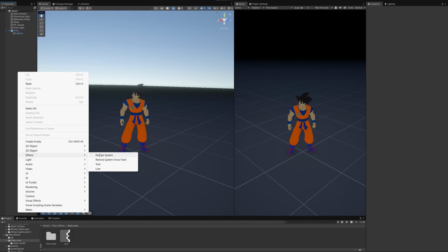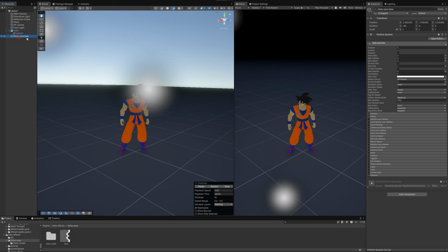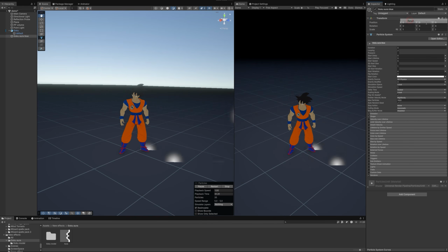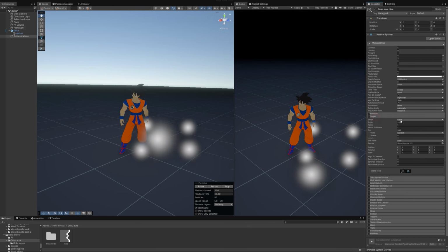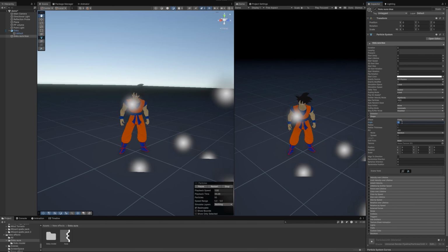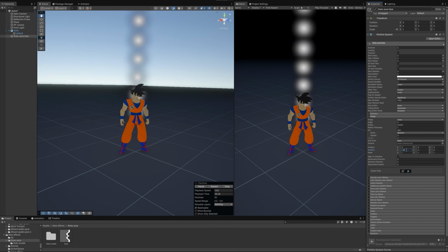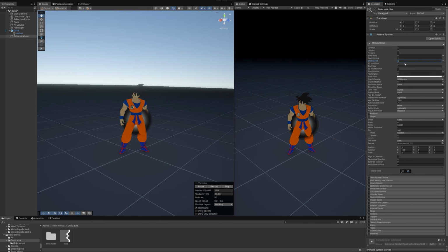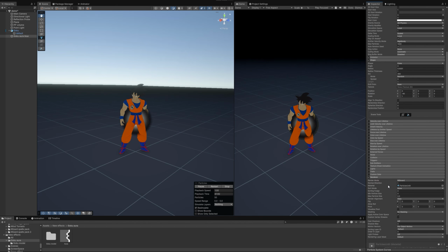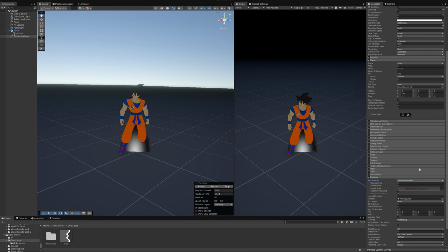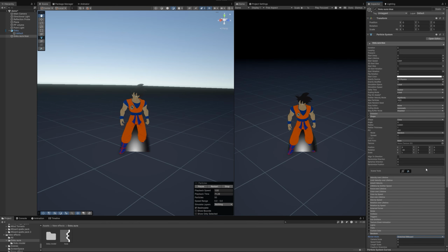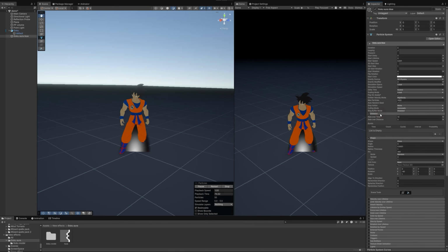Start with the particle system and move it 1 meter above the ground. Set shape angle 0, radius 0, and rotate it -90 degrees. Then change speed to 0.1 because we need to set render mode to stretched billboard, and billboard particles don't work without speed.